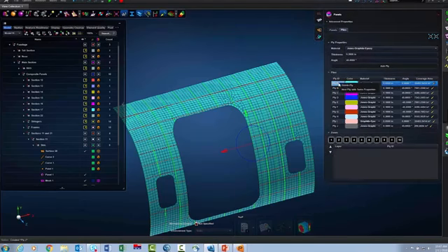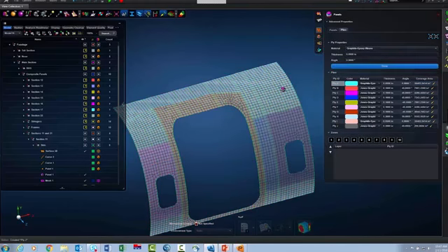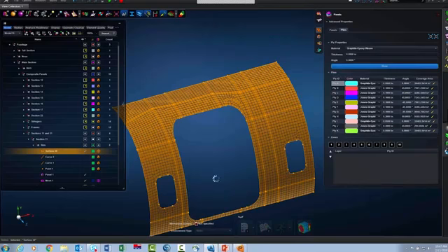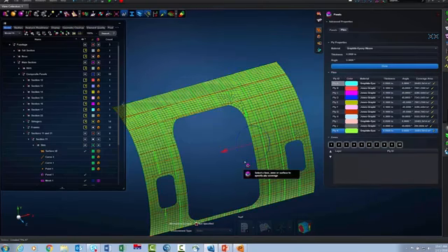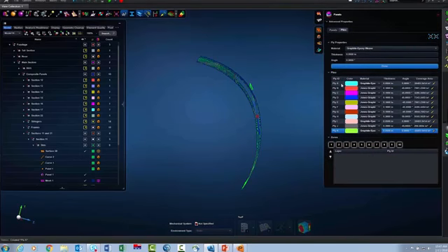So I'm actually going to add an additional ply with the same properties. I'm going to apply it to the entire panel, okay? And the thing that I noticed, remember we're kind of using a manufacturing-based approach, is that this ply is actually last. I wanted this ply to be underneath ply A here, okay? It's been added to all the zones.